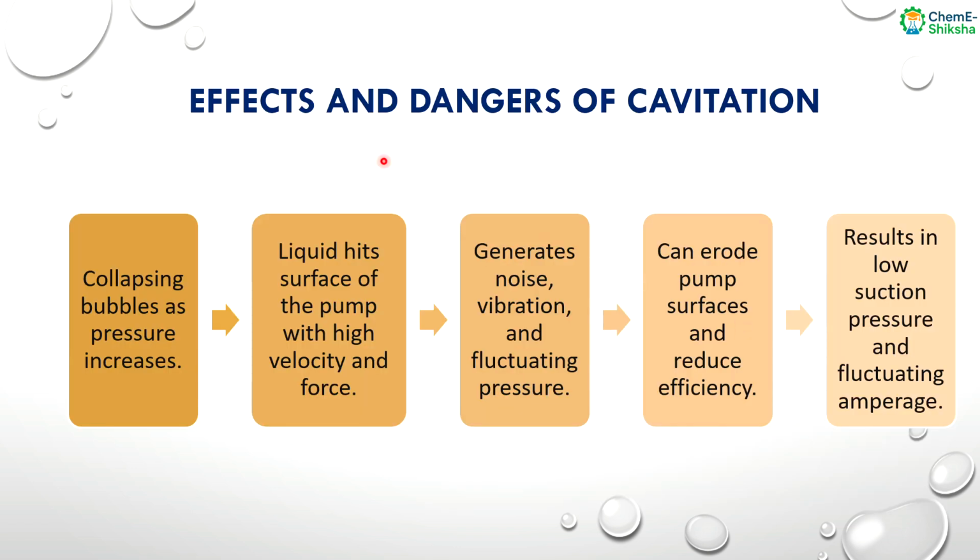So, the effects and dangers of cavitation. As I told you, the bubbles collapse as pressure increases. So the liquid from the surrounding will hit the surface of the pump with very high velocity and force. It will create noise and vibration, and it will also erode the pump surface and reduce the efficiency of the pump, and this will result in low suction pressure and fluctuating amperage.